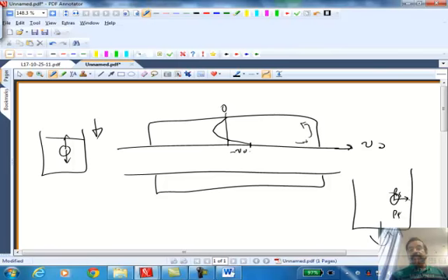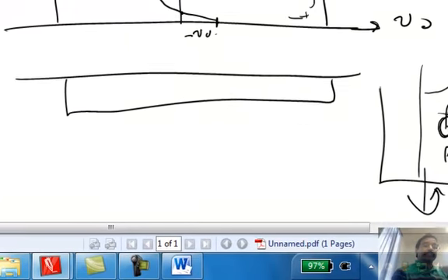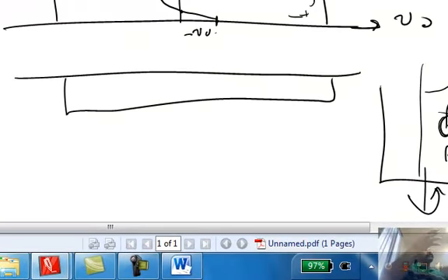The pressure force is the integration around that, which is the cause for the buoyancy force. Now you know that as you go out in the centrifugal field the pressure increases like this. In the hydrostatic case, it increases linearly down. And that's why you have a higher pressure down and a lower pressure up. The net pressure is upwards. Okay? And that net buoyant force always acts upwards, but if the weight is more than that, it's going to sink. If the weight is less than that, it's going to float.